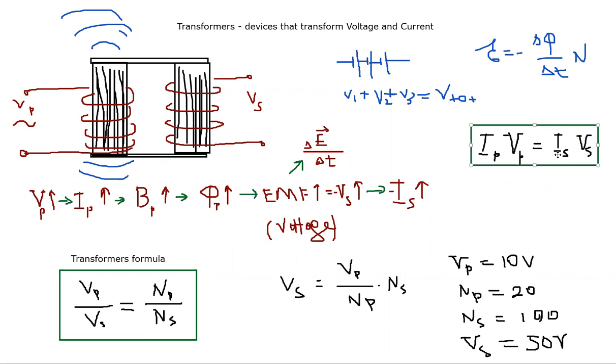So over here on the side of the secondary, you will have some sort of coefficient, which stands for the efficiency of a transformer. The efficiency of consumer-rated transformers is anywhere from maybe 70 to 80%. Transformers which are used like high-end, large-size transformers may get more than 90% efficiency.